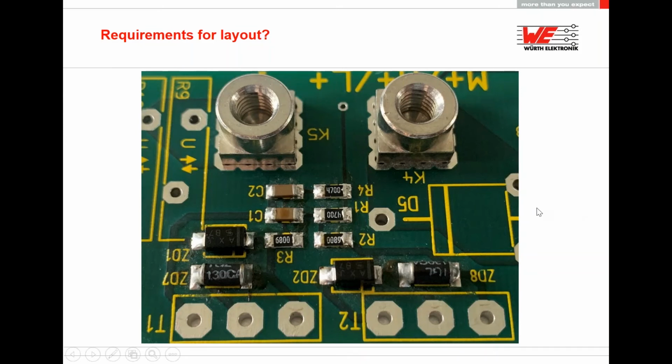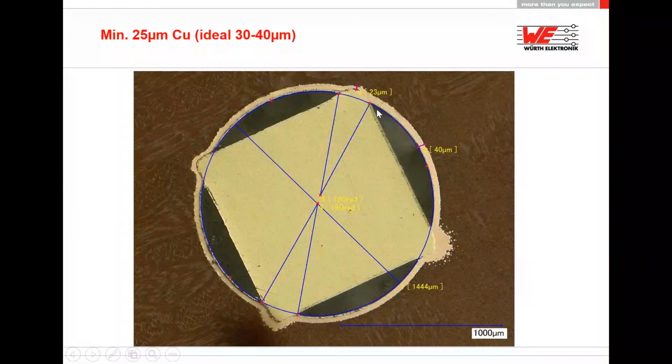Yes, of course. Maybe we go back to this one. Of course, you can press into copper bars, because the copper bar is nothing else than this one, but instead of FR4 material, you have just copper here. And it's even easier to press into copper bars or brass bars. It's also possible to press into brass bars.